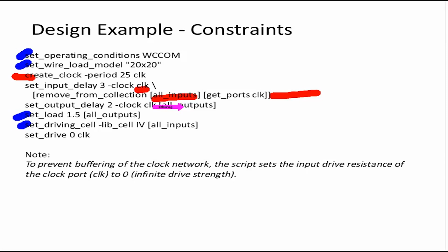So it will have a big design rule violation, a port which is driving 1000 cells. But Design Compiler is not the tool to fix those. Usually this fixing happens during physical design when an actual clock tree is built.